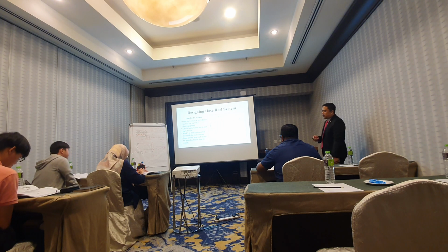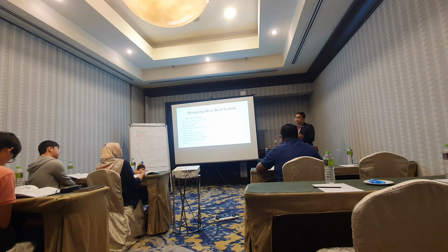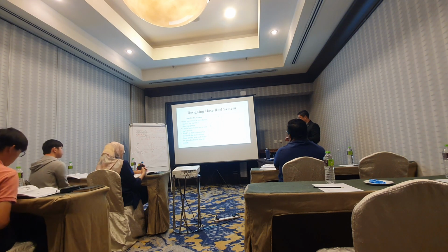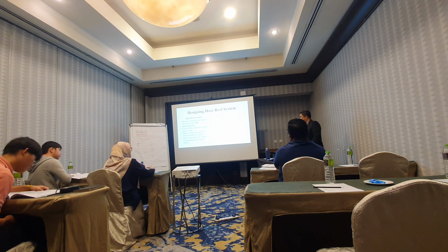Okay, after we check Schedule 10 in UBBL, we can ensure whether the building has the hose reel or not. Kalau macam building yang kecil, for sure we don't have the hose reel, right? Ada some shop lot require no hose reel at all. There are shop lot yang kena ada hose reel, if you have more than 1,000, if I'm not mistaken.